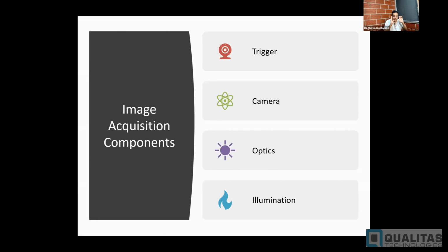So you want to make sure that there's consistent lighting. We are in a day and age where manufacturing is happening 24/7, three shifts, there's day, there's night, right? And you want to be as consistent as possible. Something that works well in the daytime should work in the nighttime, because of artificial lighting or tube lighting or overhead lighting, you don't want the camera to start taking images which look very different. So the way to counter any kind of ambient lighting variation is to have your own illumination.